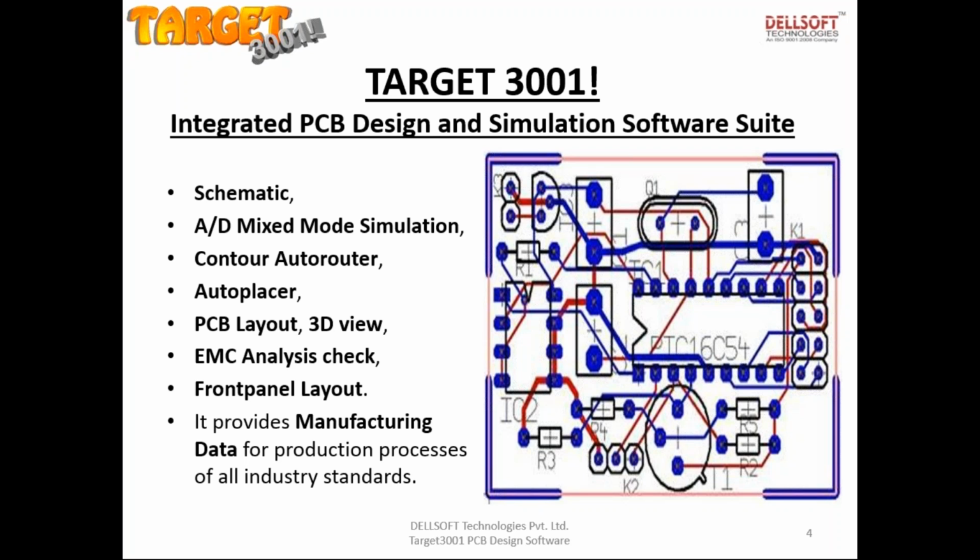So after this schematic and simulation, there is a part of layout. So we have designed the circuit, we have checked our circuit through simulation, and now we have to create that layout. So for creating that layout, this software has integrated various tools inside, that is auto placer, auto router.